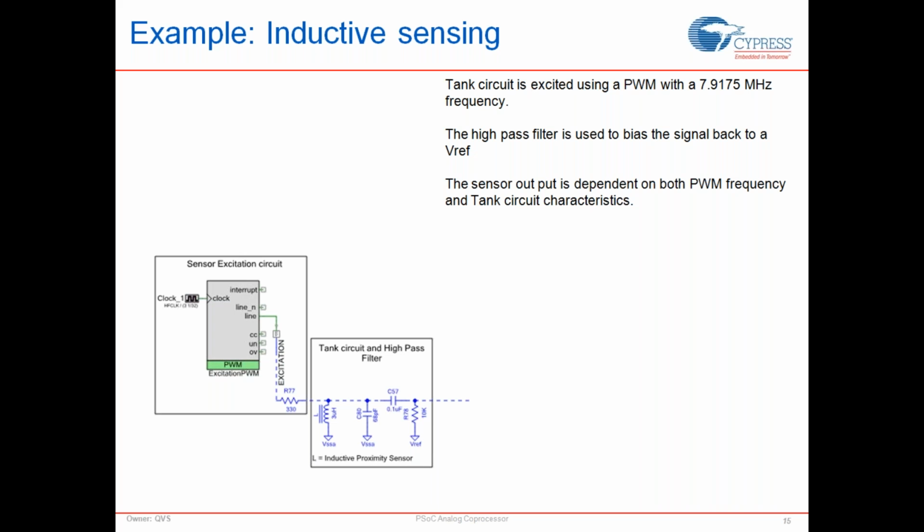So I want the variation from the 8 megahertz signal to be as minimal as possible so that my down-mixed output is a really low frequency that I can measure using my ADC in an averaged mode and still get the most amount of resolution out of it. So that's the objective. That's why you want to do a fractional divider, so that you can have a fractional variation from your down mixing signal.